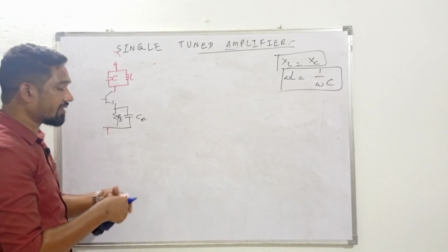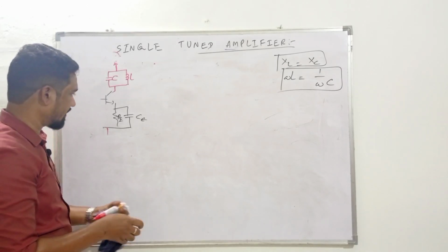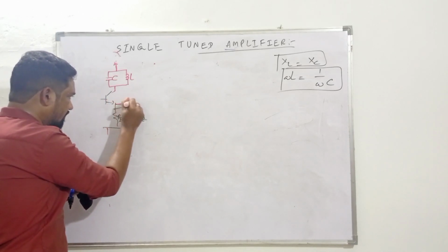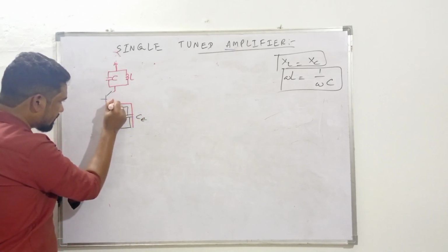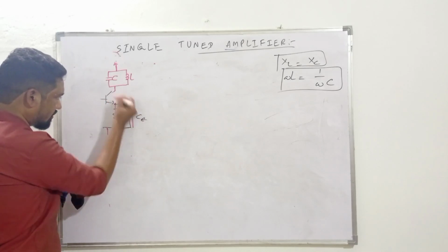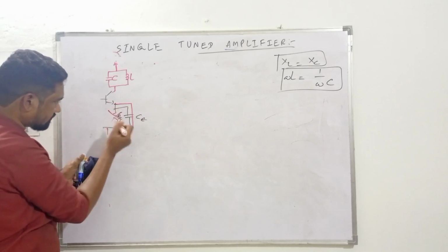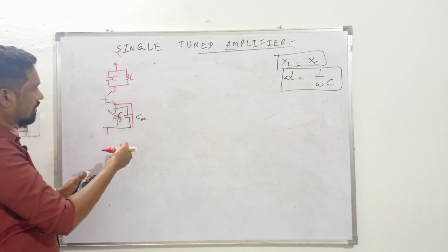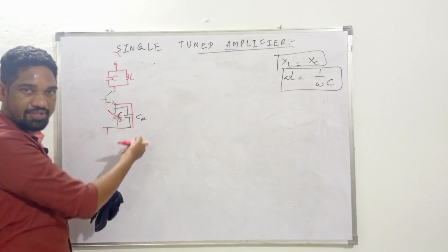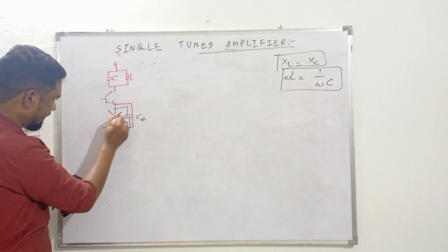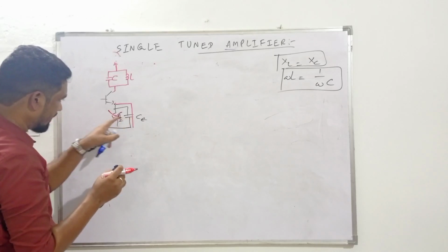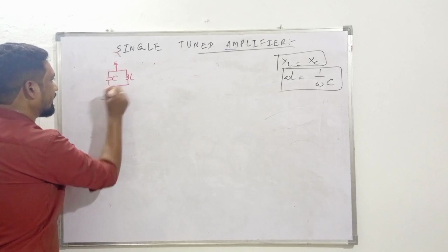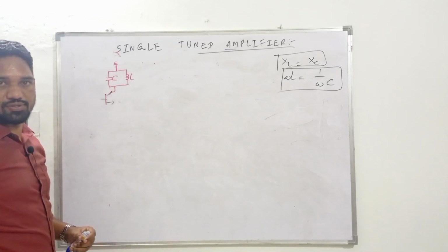And on the other hand, it's an AC analysis, and the capacitor will be a short circuit. Ground potential appears over here, so we don't have this one, because it's grounded on either side with the capacitor property for AC. So we don't have this one also. This gets short circuited. Ra doesn't exist, so we only consider this transistor and the tank circuit for the analysis.